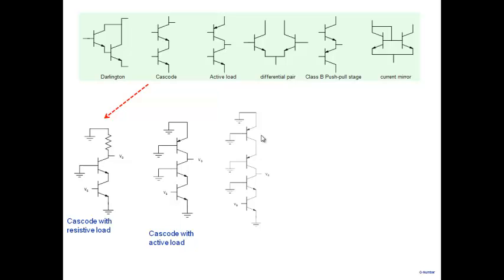Cascode connection here. And why are we using it? Well, if you look, we have been saying that the net gain at this particular point depends on the Norton's current and the Norton's resistance. Norton's resistance is resistance looking down and in parallel with resistance looking up. So in this case, if you look down, you see one transistor and another transistor, resistance looking down is very high. If you look up, then you see only the resistance of a PNP stage here. So the gain of this particular point, Norton's resistance, would be decided by this one here.